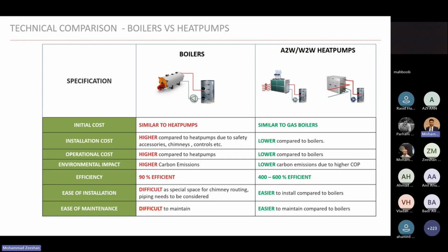Maintenance, you need a very specialized equipment supplier for maintaining boilers, whereas heat pumps are a fairly day-to-day system that is being used in each and every part of life, such as AC. So you have a lot of specialized people doing the maintenance, so it's easier as far as skills are concerned, easier to find them, and also to maintain a heat pump is much simpler than the boiler.